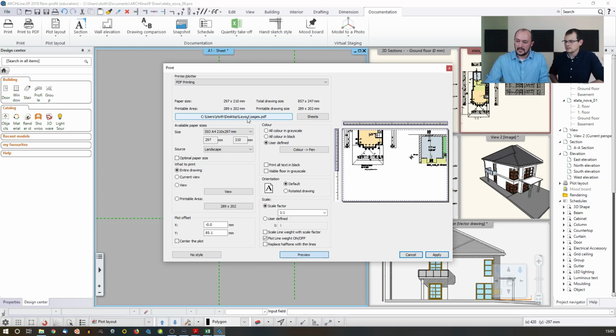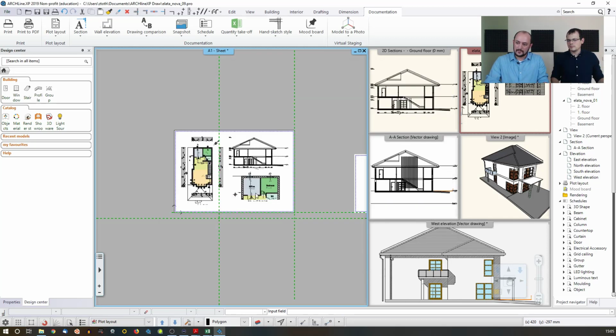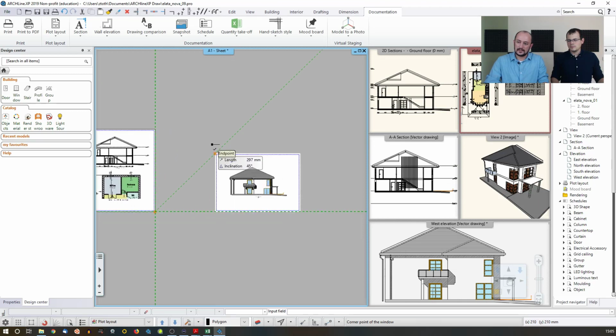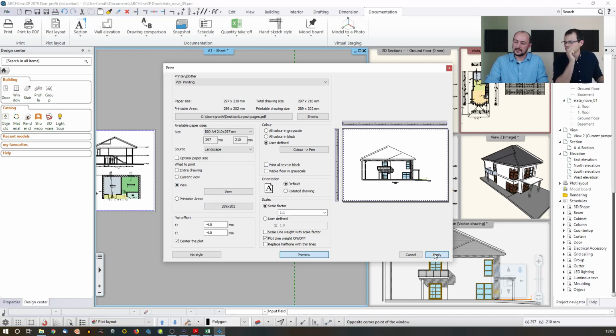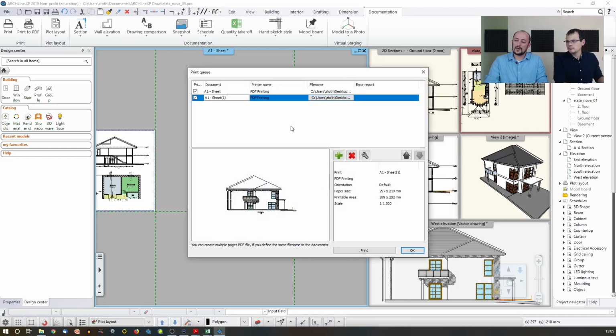And I again go with the view option and click on this one, and select the content from corner to corner from this A4 size page. And then when it's added, I will see it in the preview, and I can make it centered like that. And I think I'm fine with that. Scaling, size, and view is fine. And I click OK, apply. And then now it's something that I can print.